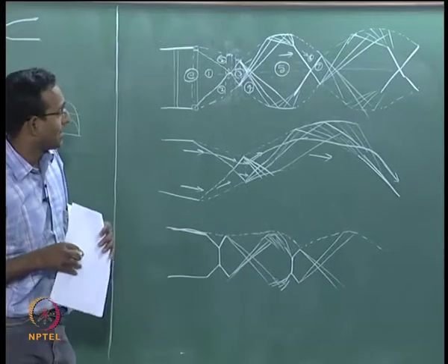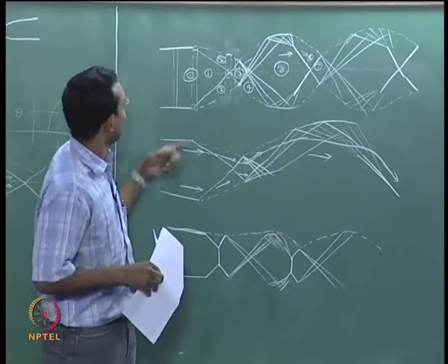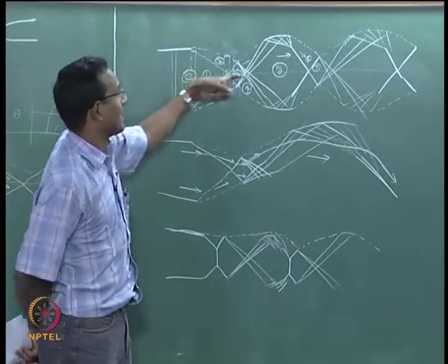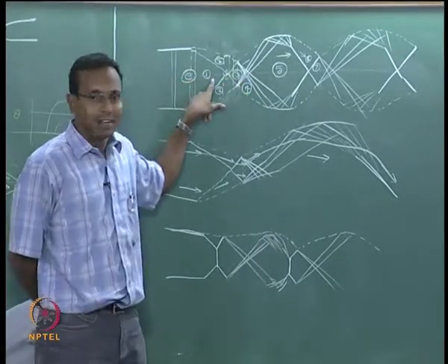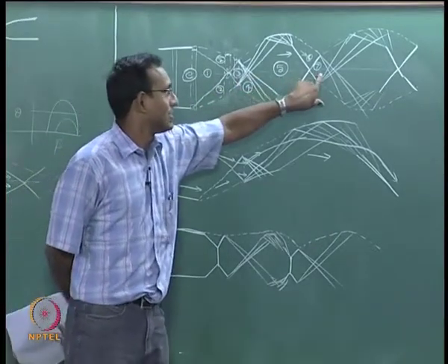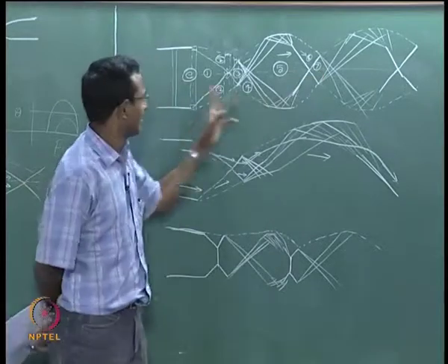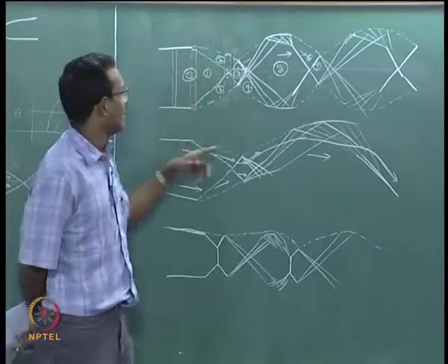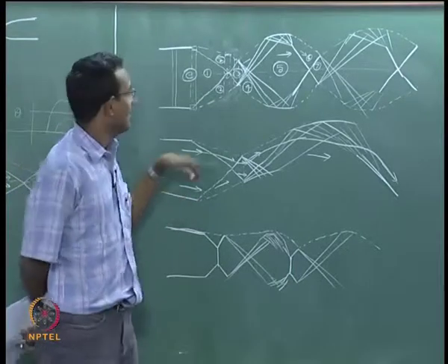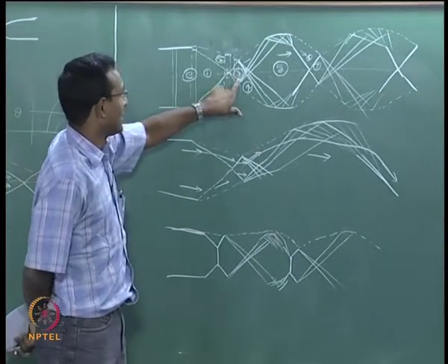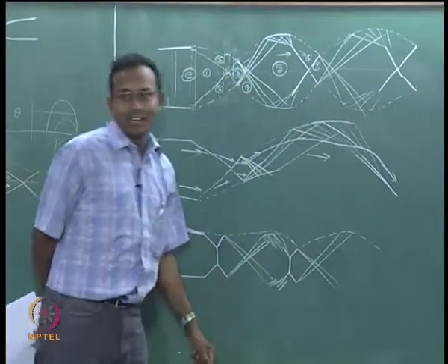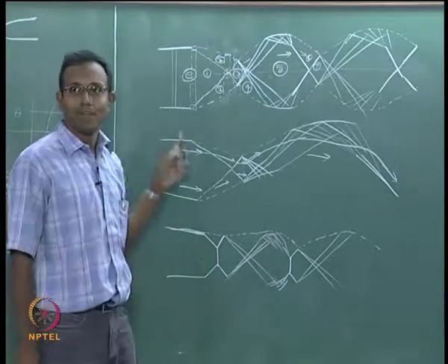If you think about the temperature of the gas along the center line, I will go back to this picture, it is nice. 1 is high Mach number, 3 is low Mach number, 5 is high Mach number, 7 is low Mach number, right, expansion versus shock. So if it is high Mach number, it is low temperature. Here it is low temperature, here it is high temperature, low, high, it just keeps oscillating. What happens because of that?